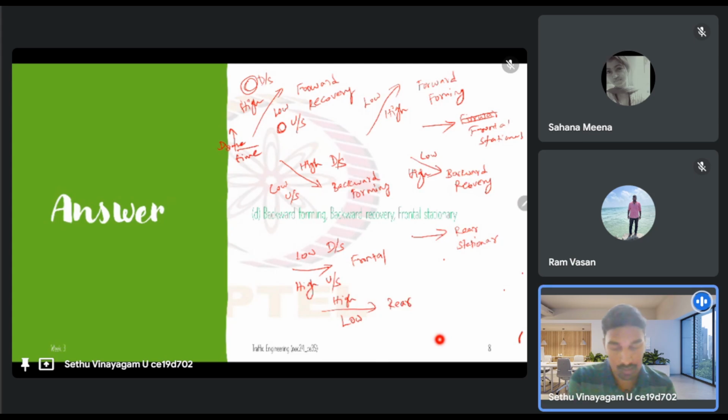Okay, so these are the six different shock waves. You just have to look at the traffic state on the downstream side and upstream side, and then the speed of the shock wave. Is it positive or negative or zero, right? So with this combination of speed and the two densities on either side of the shock wave, you can determine it.